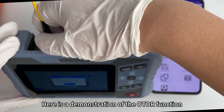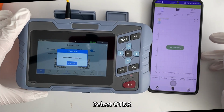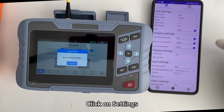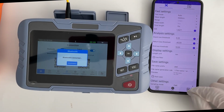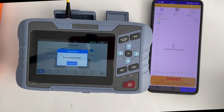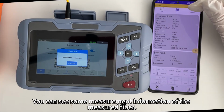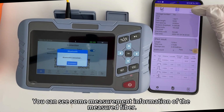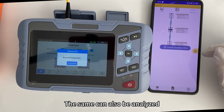Here is a demonstration of the OTDR function. Select OTDR. Click on Settings. Some settings of the OTDR can be changed. Waiting for the test to end, you can see some measurement information of the measured fiber and event mapping function. The same can also be analyzed.